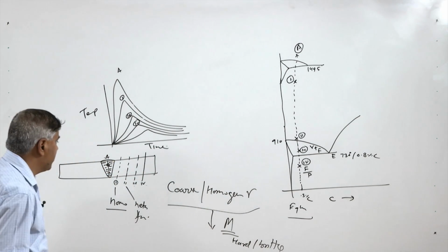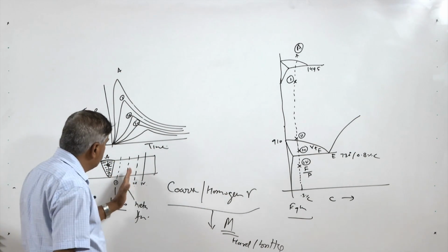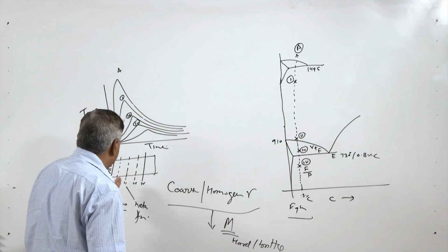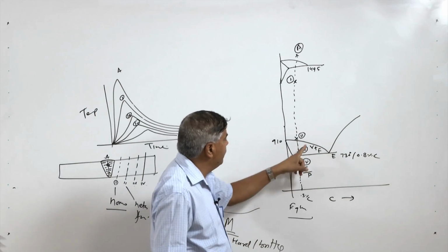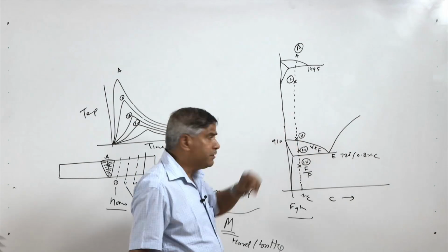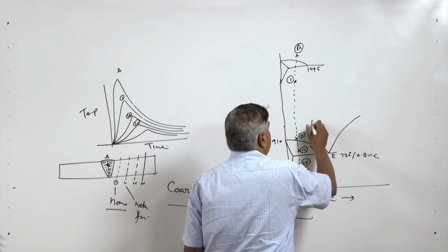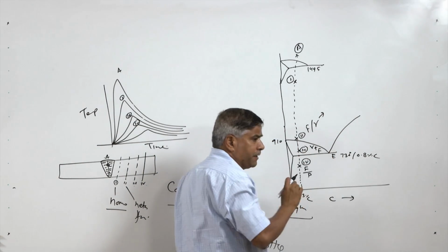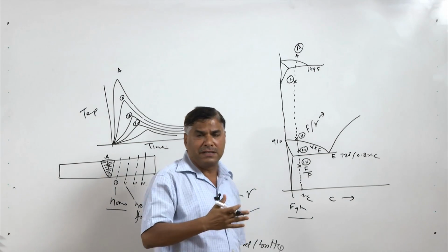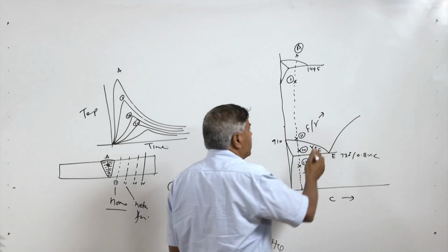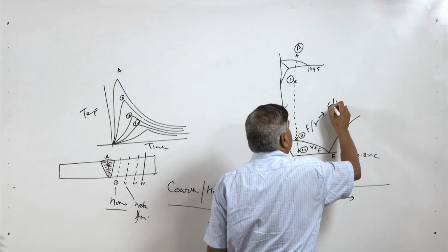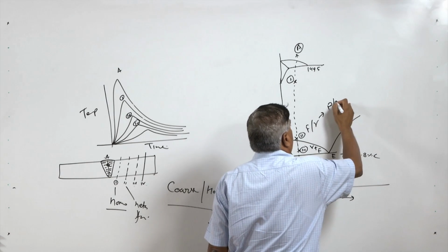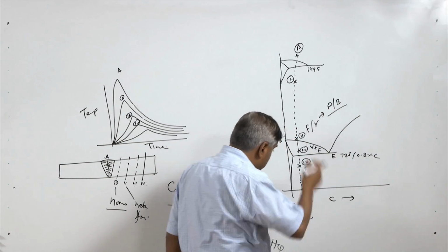So this is one typical case, while point 2, which is located further away from point 1, has fine austenite. Fine austenite discourages martensitic transformation and promotes the softer phases like fine pearlite or bainite, as per the cooling conditions.